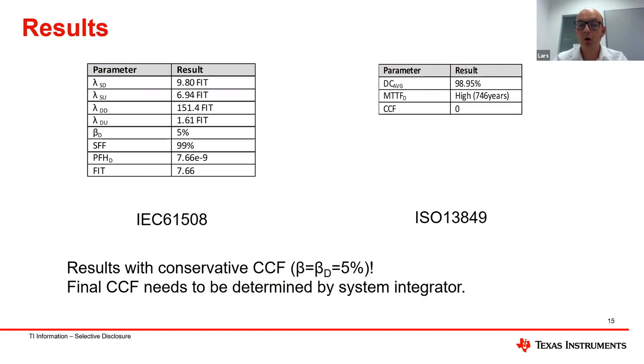So as you know, the common cause factor plays a very important role in a redundant channel system, in our 1 out of 2 system, because we need to avoid that both channels are influenced by environment or so the same way. So you heavily rely here on the comparison of the 2 channels. But if the 2 channels drift the same way in one or the other direction, the comparison is still the same, and you have a problem.